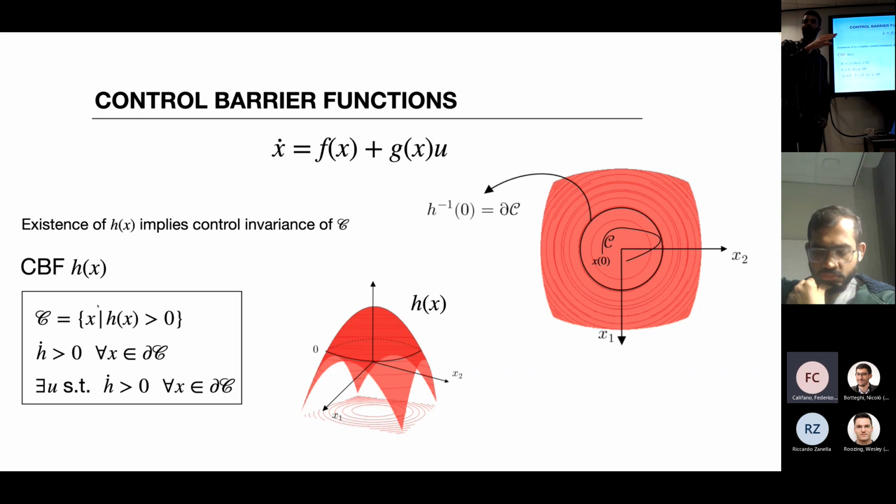This is the very basic definition of a control barrier function using Nagumo's invariance. With Nagumo, I really give the condition only at the boundary, which at the control level is intractable, because it means you do a bang control at the boundary. Basically, you do nothing until it reaches the boundary, and then you push. This is not excellent to implement at the control level. We need a smoother version of this, which turns out to be dual to the exponential version of Lyapunov stability.